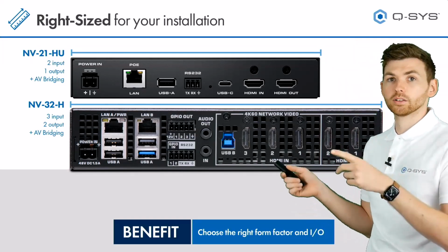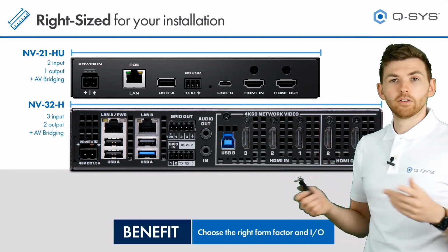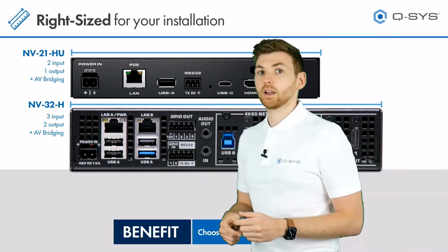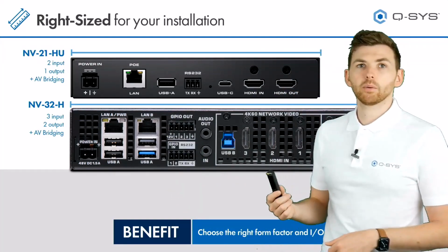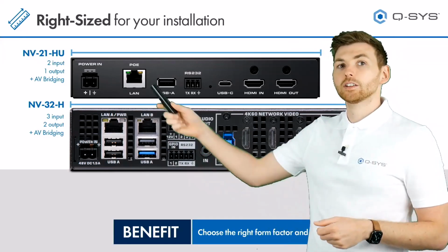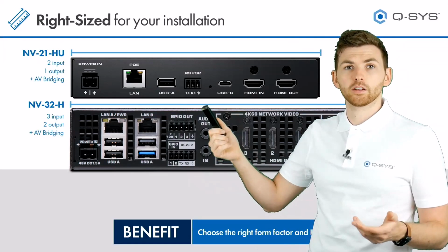So that requires a 90 watt capable output on the switch. However, you can also just connect a 48 volt, 1.5 amp power supply instead and not use PoE. Now the NV21 requires PoE++, but there's a massive range of PoE++ specs. It's the 40 watt or thereabouts PoE spec for that one.